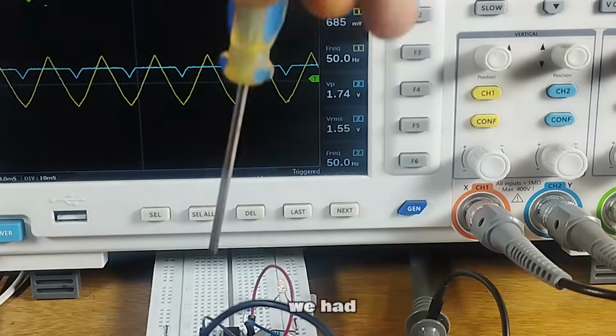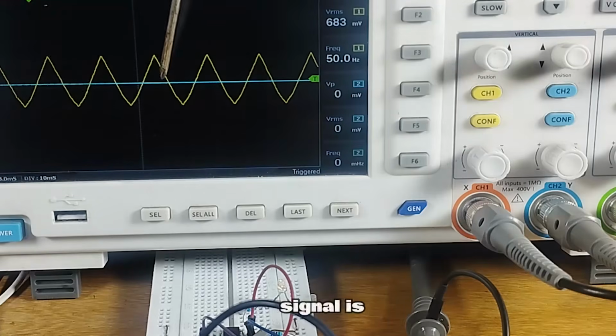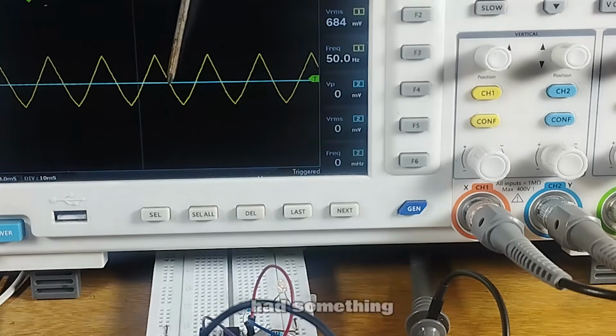Because when we had this at 0 volts, we see that once the inverting signal is higher than the non-inverting signal, we would have no output. But once the inverting signal is lower than the non-inverting signal, we would have a high output. So we had something like this. We had a high at this point, because this is the threshold at which the output is triggered. Just below this point is where the negative pin gets lower than the positive pin, and so we would have an output voltage. We have that trigger of output on, and it stays on up to this point.